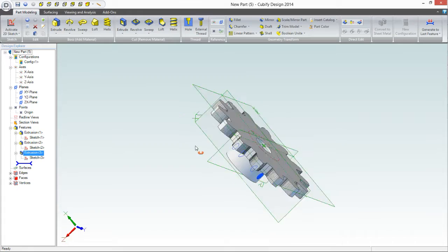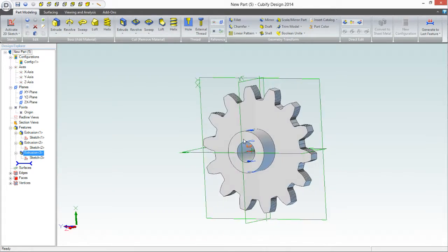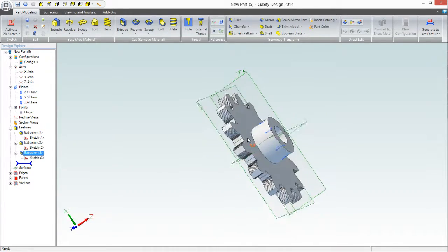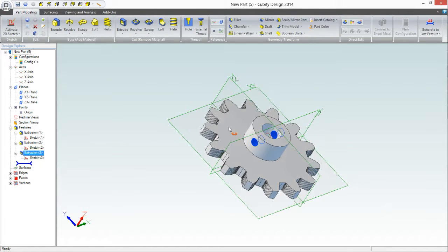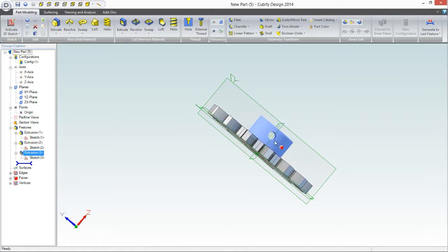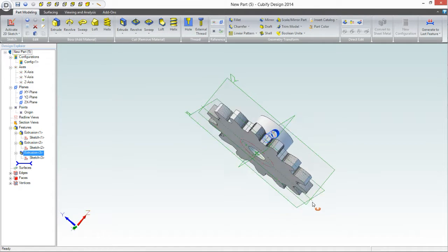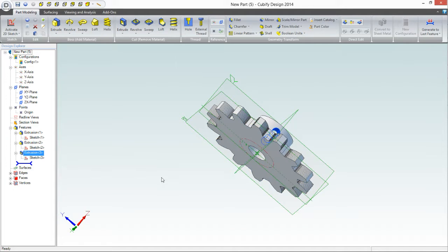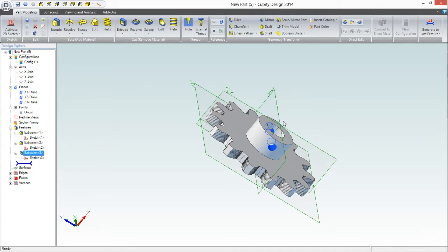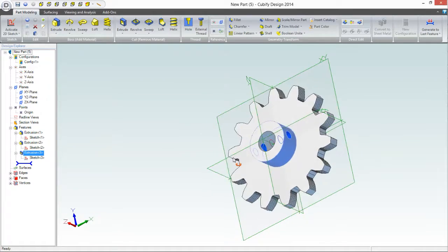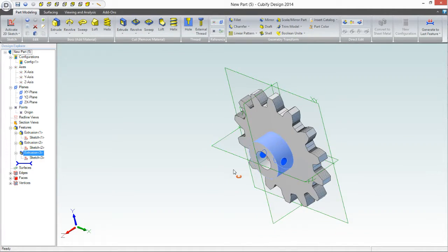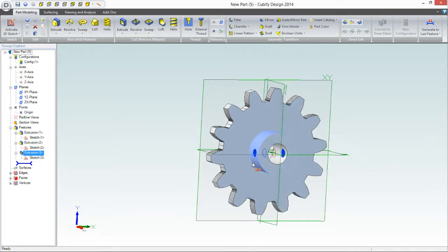Now I can lock the gear to a shaft. See there? Got a 14-tooth locking gear shaft. And when I print this in the 3D printer, that hole will be accurate enough. It'll print it, of course, from this flat face up. That hole will not be perfect, but it will be good enough that it'll guide a drill bit straight through that little hub. And now I can lock that gear onto my shaft.